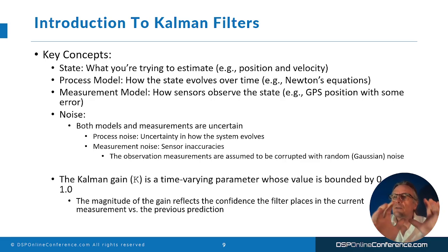And the answer is we use the variance of the signal. What's variance? It's the noise within the signal. How much does the signal vary? If a signal has a high level of variance, it has a very high noise level. So the estimation from a single input sample, for example from a noisy transducer, is going to be less accurate than from a very high quality sensor with a very low noise level.